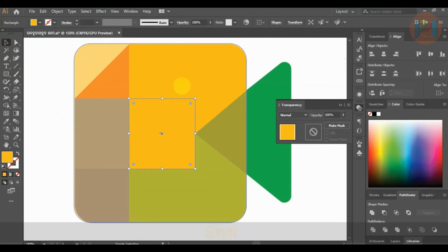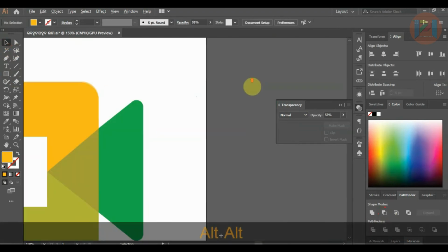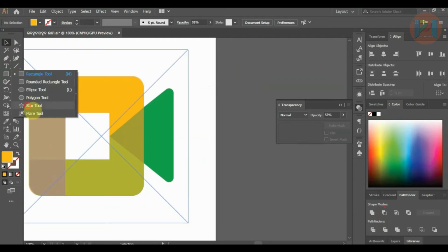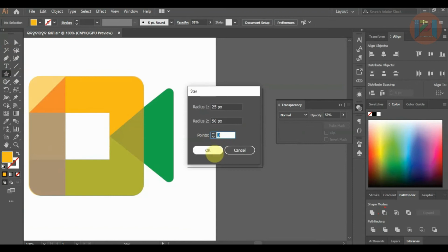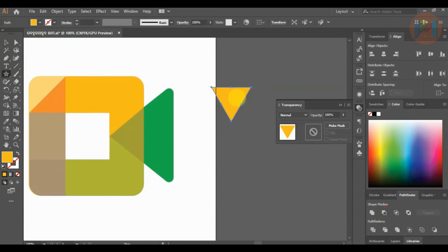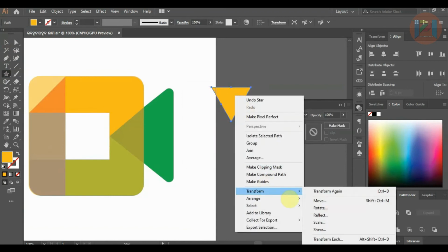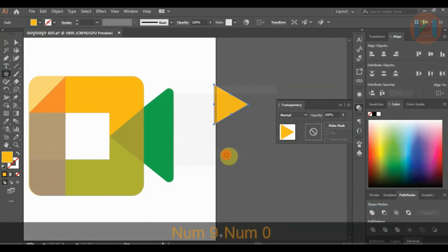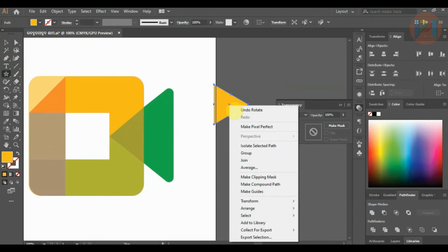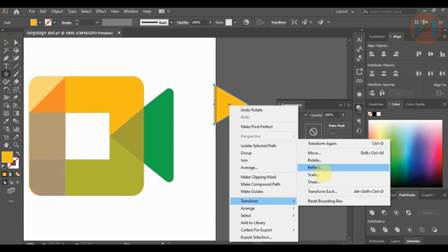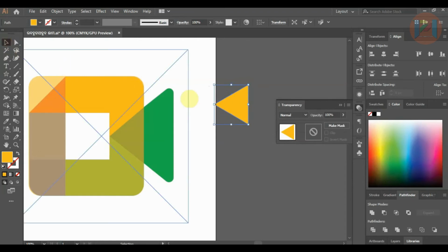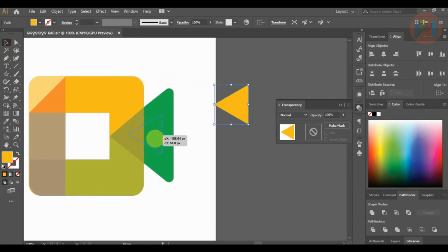Select the outer rectangle and inner rectangle and click on minus front from Pathfinder. Next, for the extruded part, I'm using a rectangle, rotating it to 90 degrees. Again, it needs to be reflected vertically. Now it's done. So here I'll adjust the shape.